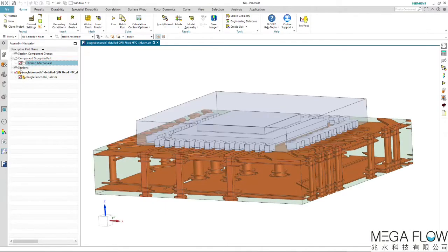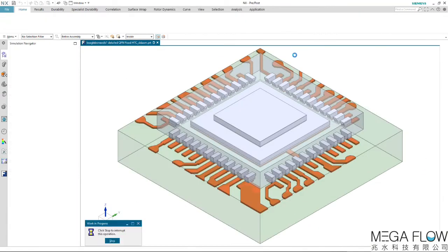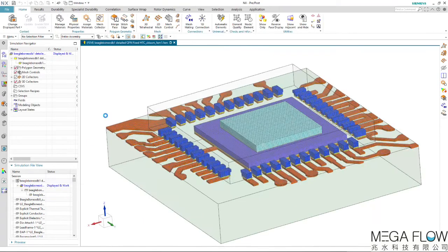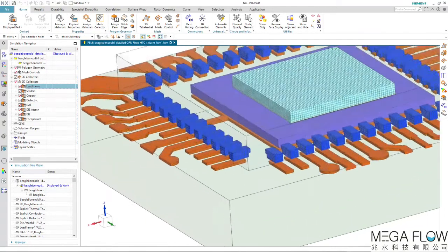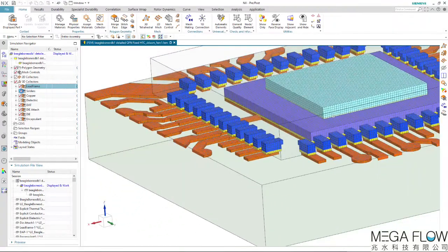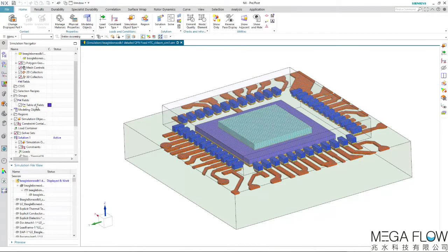The Simcenter Flotherm XT simulation considered all layers in the thermal territory as explicitly represented, which provided the most accurate temperature prediction. For the thermo-mechanical simulation, the top layer will be considered along with the relevant QFN structure to do the thermo-mechanical analysis of the solder joint. The interface between the components are solved with the contact type gluing.